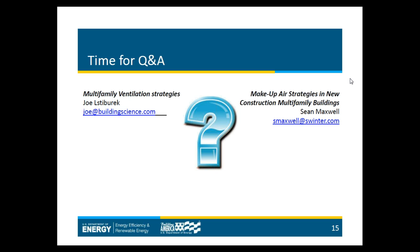Thank you. And now I have a few questions for Joe. Can a balanced system operate intermittently and still be effective or compatible with multifamily buildings? Yes. What's nice about balanced systems is that since they don't affect the pressure in their individual compartment, they won't affect the pressures in the neighboring compartments. It's as if the compartments don't know that they're beside one another.